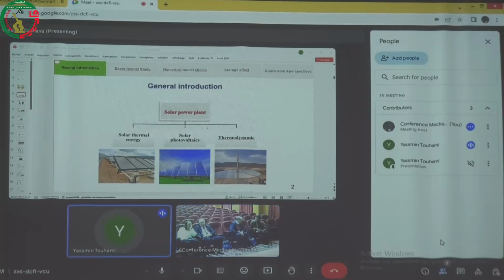Its principle of operating is very simple. An absorber painted in matte black absorbs solar rays, which are transmitted through a transparent window. Then the absorber converts this radiation into heat and transmits it to the air, which enters at ambient temperature and leaves after heating. This useful heat can be used in a variety of applications such as domestic heating and industrial applications, including drying nutrients or interior painting.